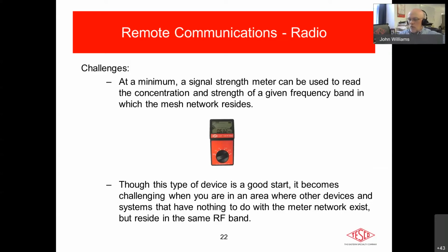And basically what that means is the mesh will work in a particular band. So if it's having trouble at a certain frequency, it can hop between different frequencies within a certain band to be able to mitigate the problems with RF noise, or RF interference, I should say. But I believe, John Carroll, if you're on, I think you have an example of that for me, do you?